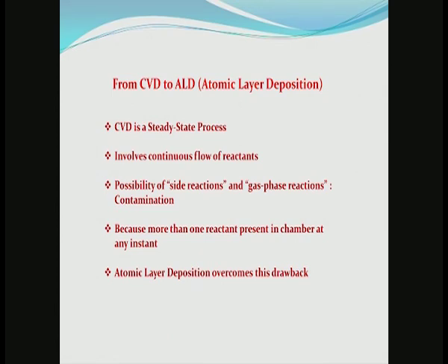Now, we move from CVD, of which we have learned some capabilities, to atomic layer deposition or ALD. Before we go, we recognize that CVD is a steady state process. It involves continuous flow of reactants, and therefore, there is the possibility of side reactions or undesired gas phase reactions, which can produce byproducts which can contaminate the film that one is interested in obtaining. That is because more than one reactant is present in the chamber at any instant. Atomic layer deposition is designed to overcome this particular drawback.